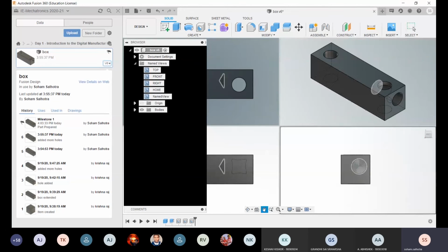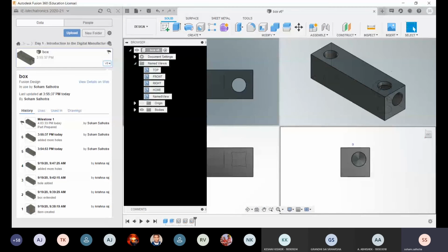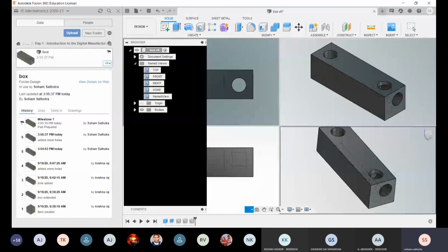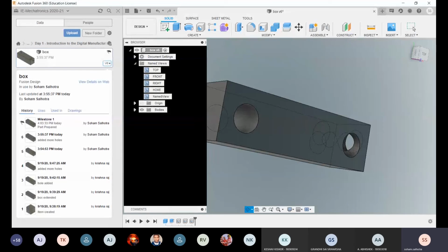And here you can pan and orbit each one as per your desire, so that you're able to see every piece clearly while making changes if necessary. You can also desynchronize them, so changes in one do not necessarily affect the other. And you can return by using the single view option on the same menu. That is right here. Now it's multiple views. When you're in the mode, it will show you single view mode as well.